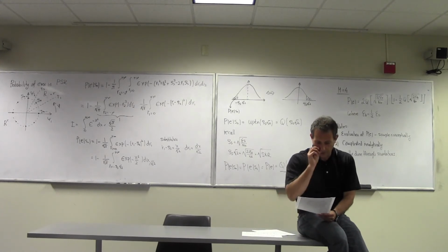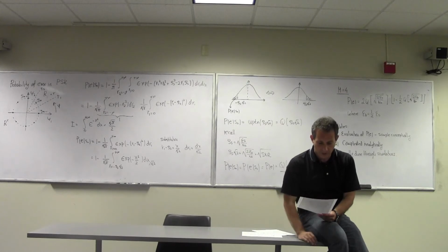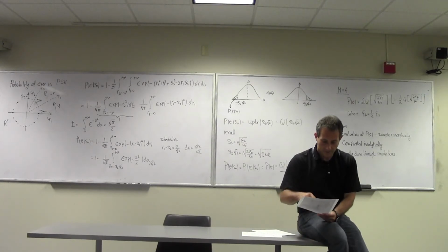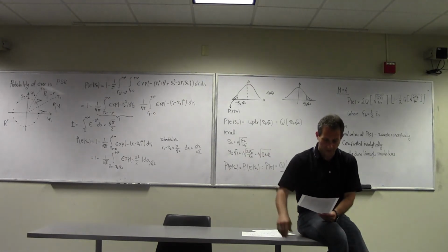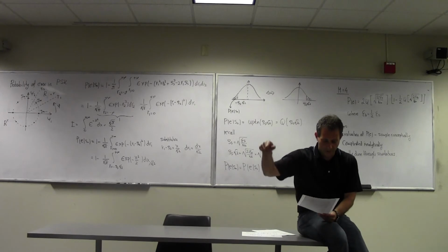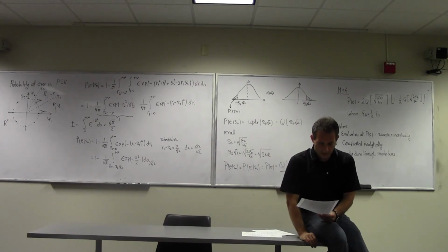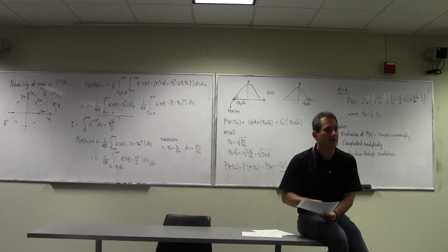So for every m, let's say m is already picked. I pick a particular symbol here, and then plot here is just turning on and turning off the constellation. If you make plot equal to 1 in the second line of the code, you're going to get the constellation plotted, and I assume also those clouds that I talked about. And then here I generate n0 based on an Eb/N0 ratio that I have. Then I set error counter equal to 0. And then for k equal 1 through n, I'm actually throwing darts. N is the number of darts.